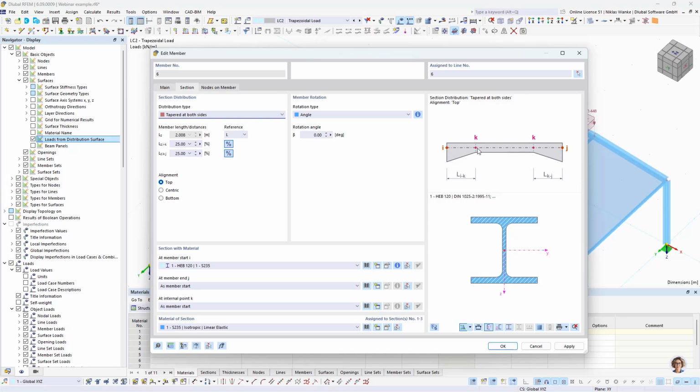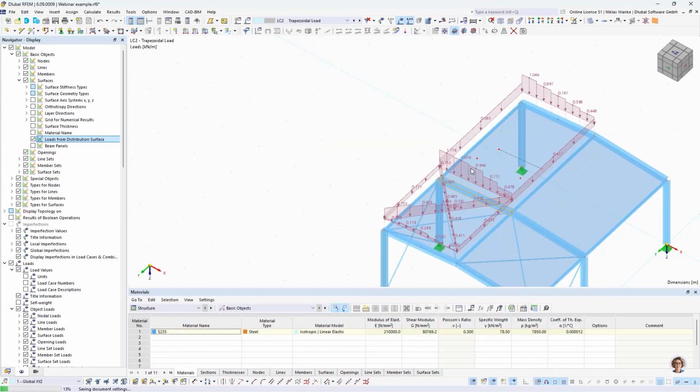If you enable the option, then for the tapered ends, the middle of the cross-section height would be applied. So in this case, the axis would have a little pitch. This can lead to small differences between the load transformation, but the difference should not be too big for most cases.